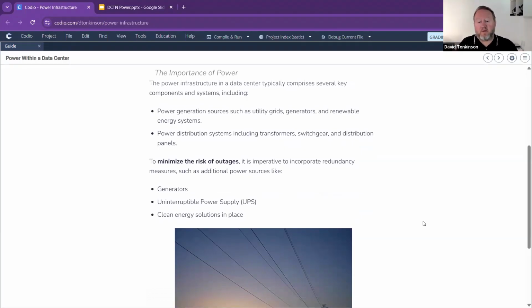Generally, we all know we deal with electricity that comes off the national grid. So if we're a data center, we would probably have two pipeways coming in from the national grid. IMART had two electricity systems coming in from two separate local substations, and they came into the building from two separate directions. So someone with a digger couldn't go through both, because they'd have to dig two separate holes. That's an example of building in some redundancy. Yes, it cost them loads of money to get it put in to start with, but the benefit of having a second source is essential.